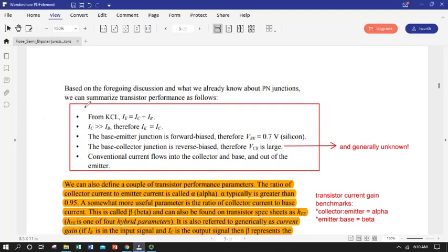So at this point we understand a little bit about the material science of how a bipolar junction transistor differs from a diode. It's got two p-n junctions just like a diode, but because you've got that thin, very lightly doped base, it's going to work differently from the standpoint of charge that's transiting the device emitter to collector, which is really our main circuit. We've stated the relationship between charge flowing into the base and the ability to get charge across the device emitter to collector.